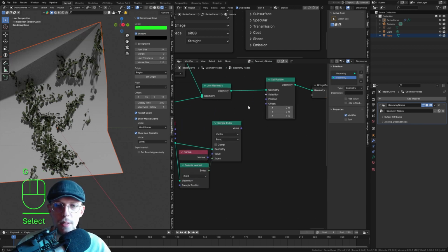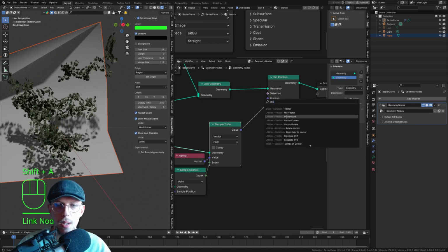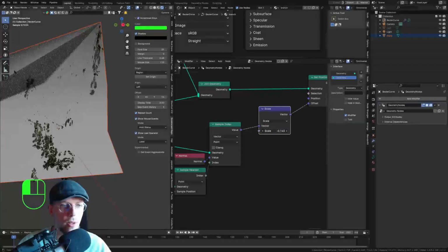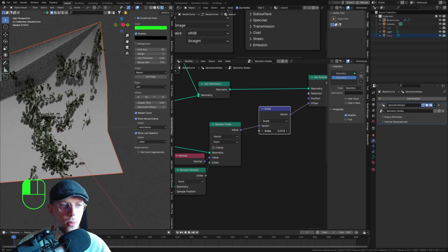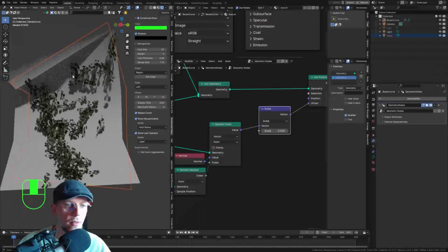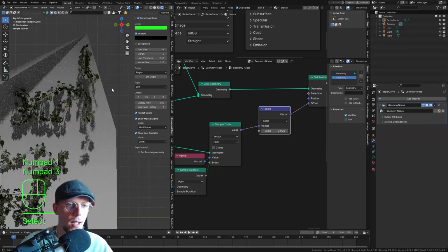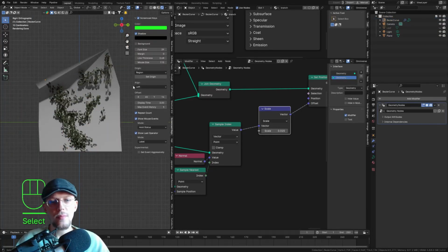And I want this to be a little bit of an offset in the normal direction. There we go. Vector math, and set this to scale. And now we can control how much of an offset it's going to get from that normal direction, right? I would recommend sticking to lower values. Perhaps 0.03 works fine. So it still sticks to the surface, but it's a little bit of a distance to add that failsafe. Maybe 0.02 works fine. And there we go, your own little scatterer.